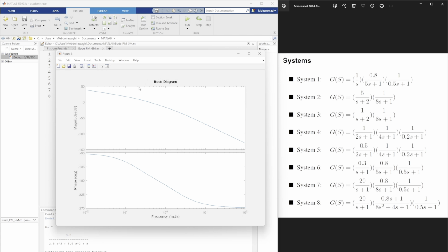So we can manually start using the definition of the gain margin and phase margin to find out what those values are. And essentially, gain margin is where the phase hits minus 180 degrees. So we find the frequency of around minus 180 degrees, and evaluate the gain at that point, roughly minus 9.